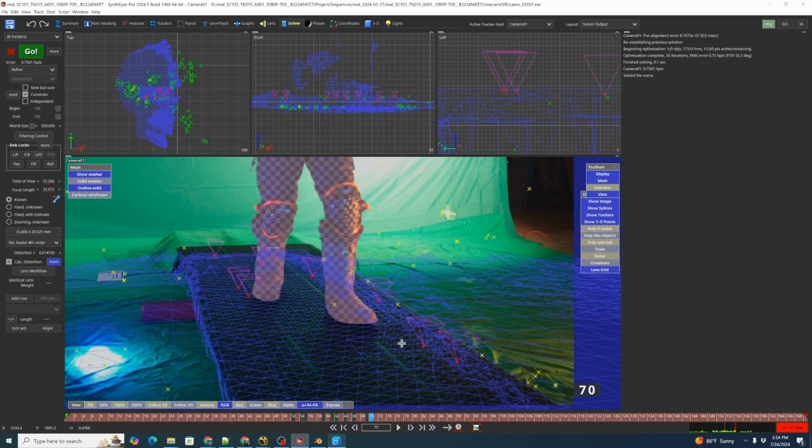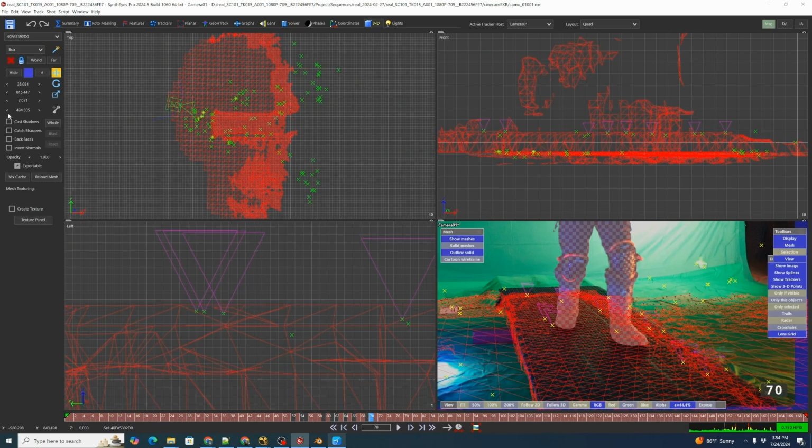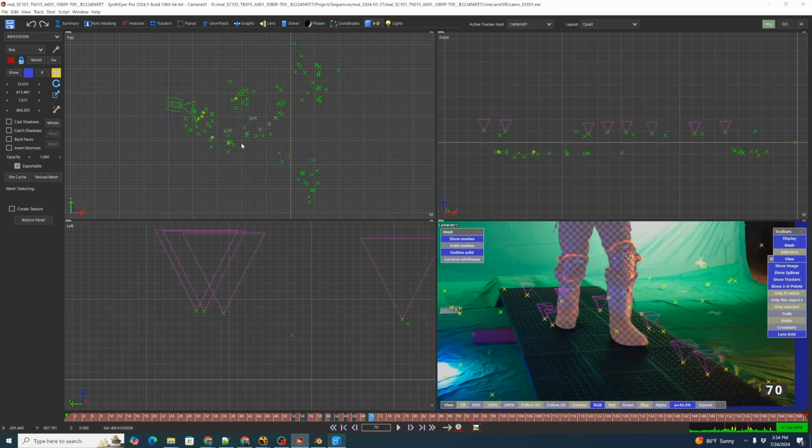One of the last things we're going to do is, once we have our ground mesh, we can go ahead and go into 3D and just click hide on that. That way we won't see it. It's a good time to save. Let us do a render so we can make sure that our 3D points are sticking correctly. To do that, we're going to do a render preview.